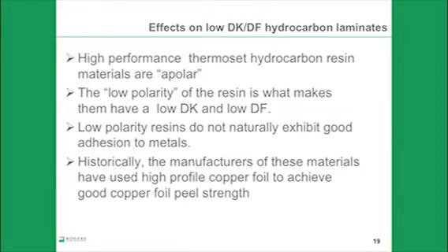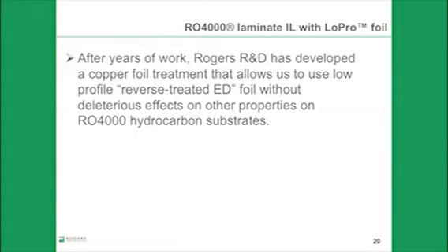After years of work, one of my colleagues, far more brilliant than I, in Rogers R&D, has developed a copper foil treatment that allows us to use low profile reverse treated ED foil without deleterious effects on other properties of the RO4000 hydrocarbon substrates.